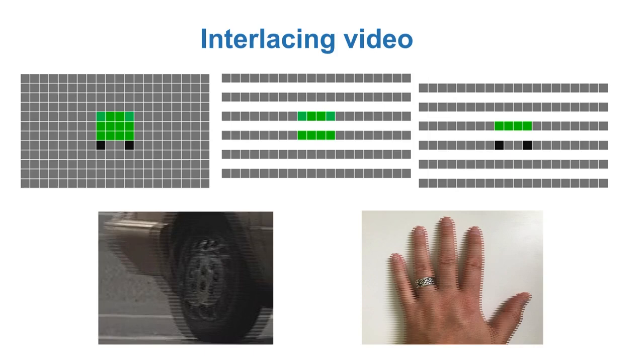What is the issue then? Well, similar to the rolling shutter, when an object is moving, the two images will not be captured at the same time and seeing the same scene. As you can see with the hand image, which here was moved in front of a PAL camera, the result is jagged edges. The image is a composite of the two separate every-other-line images, taken some time apart. In the automotive industry, this typically means blurry images. Here, an example of an image of a car wheel. There are techniques to perform so-called de-interlacing. However, if the image is compressed, the jagged edges become blurred, and such techniques are much less effective. The bottom line is, if you can avoid interlace, do it.